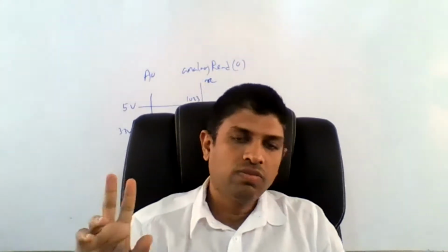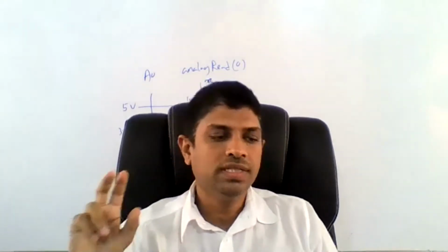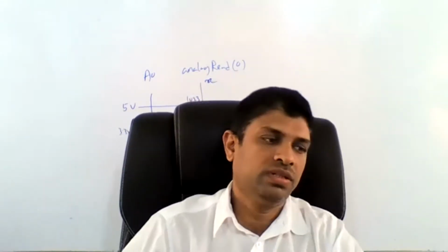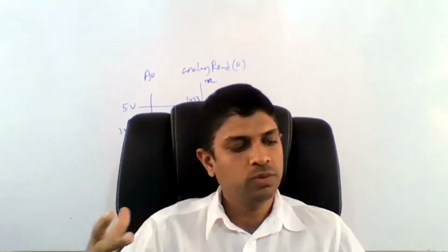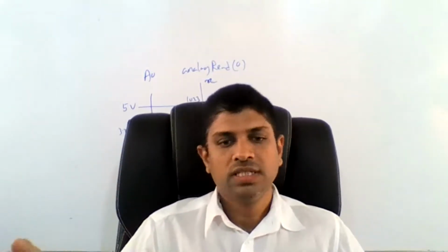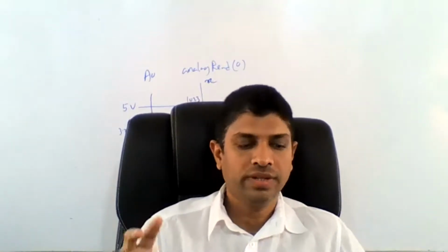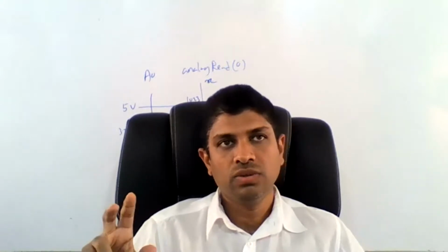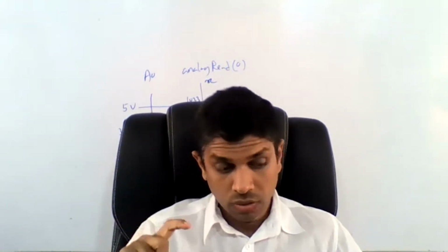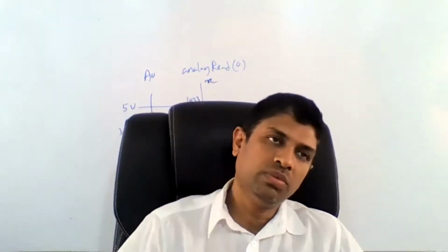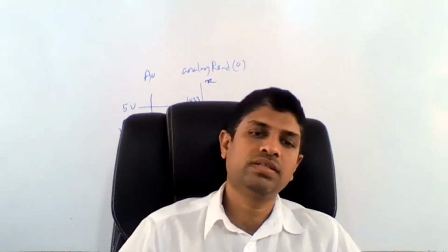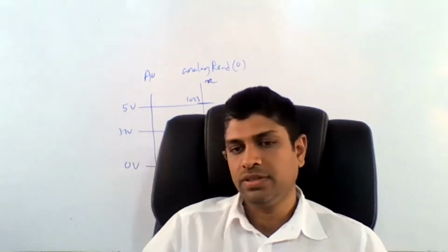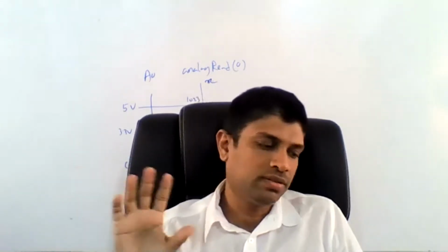Okay. So far we have discussed how to use the digital port. Digital port we use both ways. As an output, earlier we used it as an output, then later we used it as an input, right? Today we learn how to use digital inputs. Also we learn how to use analog inputs. So the analog input range is 0 to 1023. When voltage is 5 volt, it is 1023, that's what we discussed.